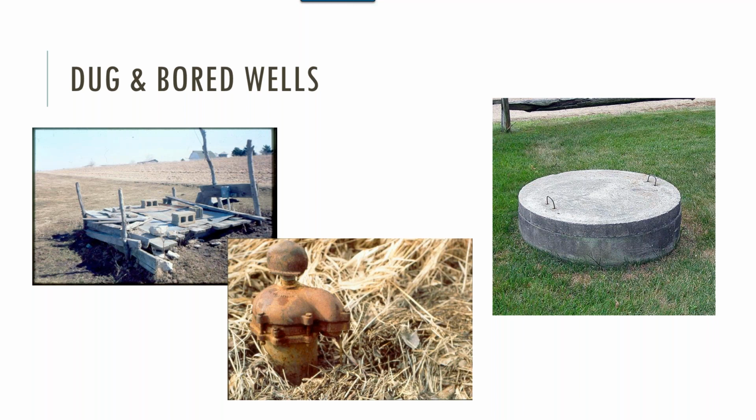And that helps protect a little bit from surface contamination or surface infiltration into the well. Whereas the one on the right here, if that's a 4 foot section of tile and it's a foot above land surface, that means water can seep in at 3 feet below land surface. And that's pretty shallow, even if it's a tighter soil at the surface to let infiltration in. Much more likely to have something from the surface that gets in your well.